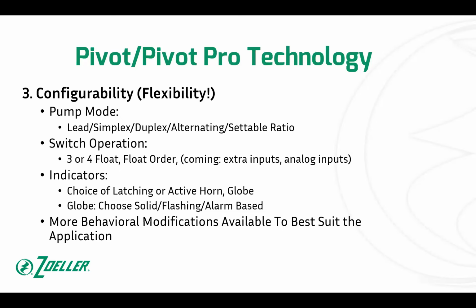For those of you that have never been in the field, a duplex panel, when you want it to operate as a simplex, which isn't uncommon, that's a real thing that happens often because you're having a pump down for service. You have to rewire the float switches. Most guys that don't work in the field don't know that, and it's a hassle. And it always seemed kind of ridiculous to me that we couldn't figure out a way to have these panels be smart enough to recognize that they're in a simplex mode now, but that in fact is not the case.